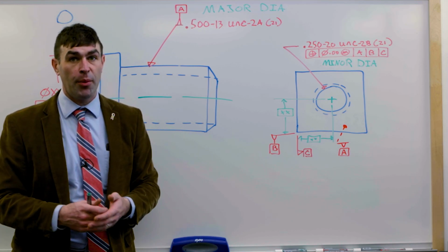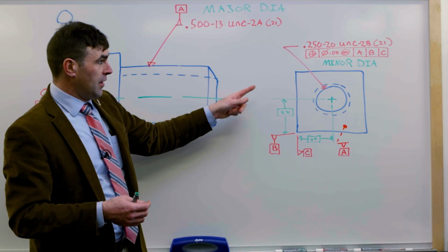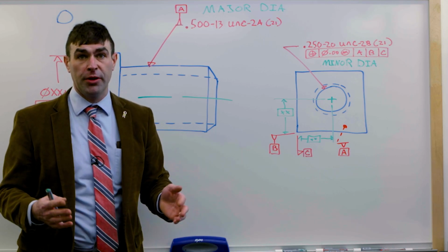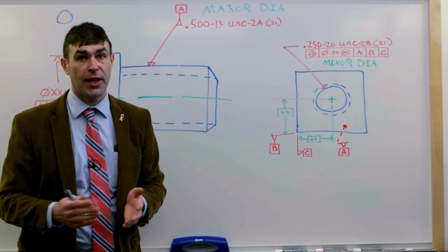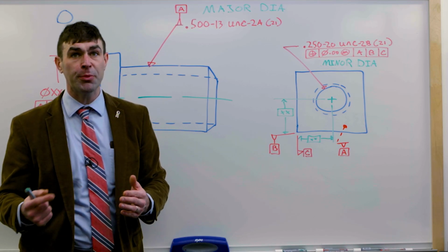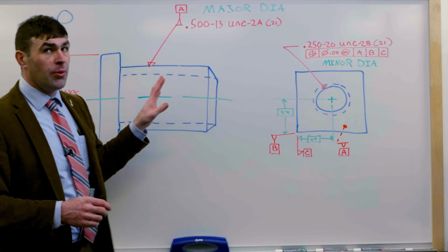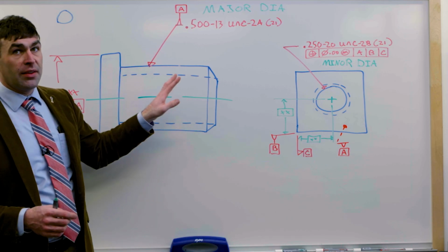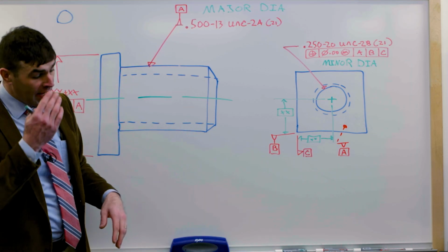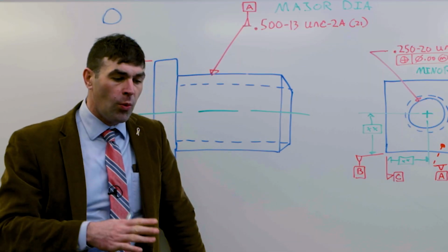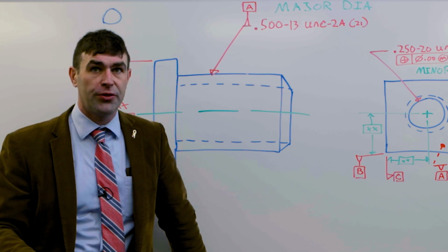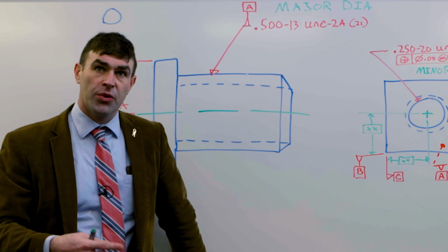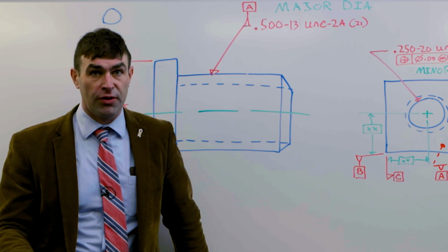of the minor diameter, which, in the 1/4 inch, can be accomplished with a gauge pin, just like measuring the axis of a plain hole. Much, much easier. But you need to specify this on the drawing. And you might ask, well, why is it the way it is? Why is the default so difficult?